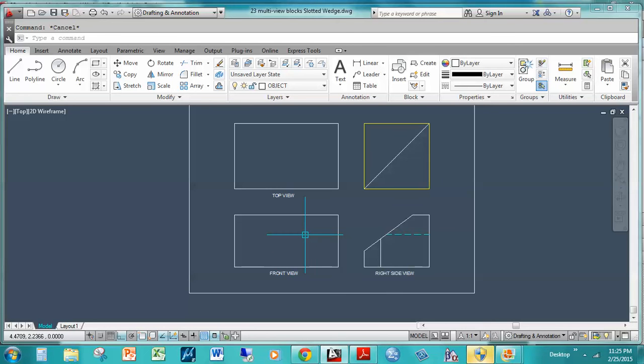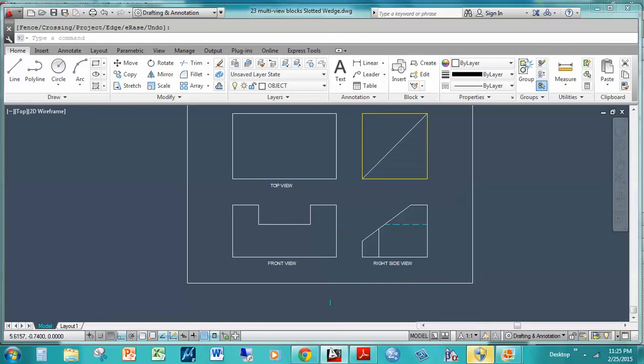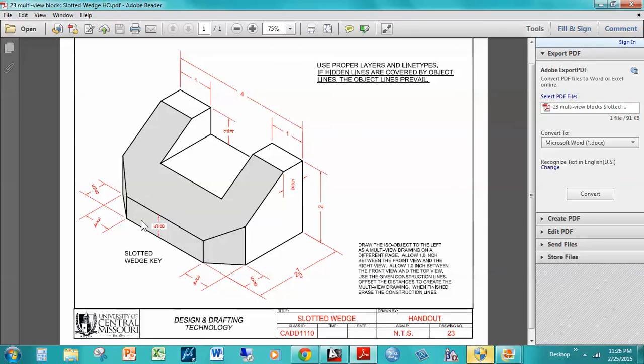Okay, so line, enter. We can draw a line on top of the existing lines with the same layer. So 1, and then we go down 0.75, we go right 2, we go up, snap to perpendicular, trim off, TR, hit enter twice. So the top part is done. Then the bottom part, from here to here is 5/8, and we know from the right corner to this point we have 0.75, and from left corner to this point 0.75.